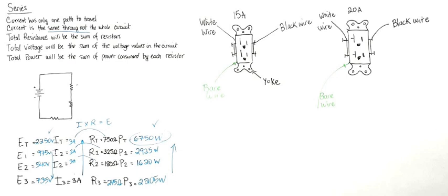The same thing will happen with current. So for current, it's the amp, the ampere. This is how we measure. And we have to have our loads on to be able to measure an ampere. So I can't measure an ampere if my load is not on. I have to have the circuit on and the load turned on so that I can take a measurement, because I said yesterday that our electricity is invisible. So unless there is a flow, then we can't use our measuring tools to be able to measure.